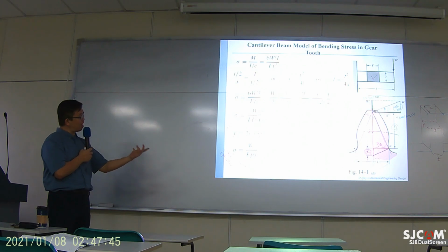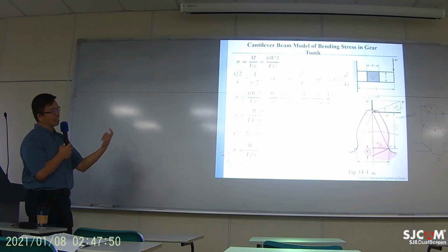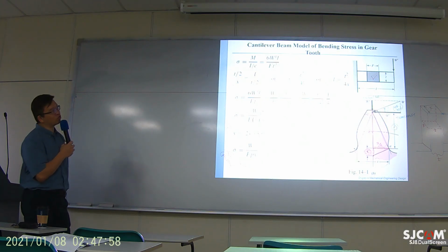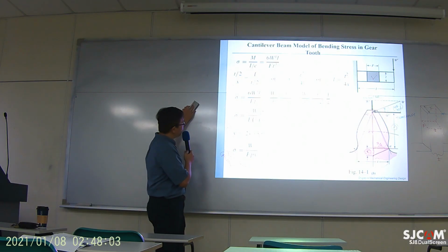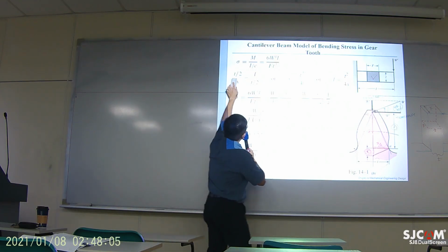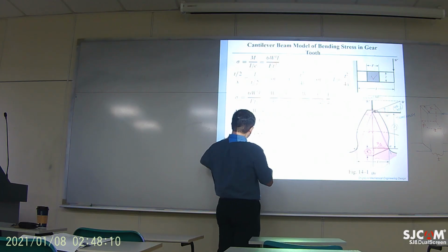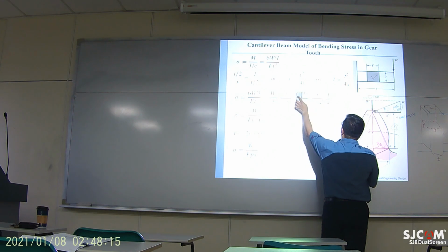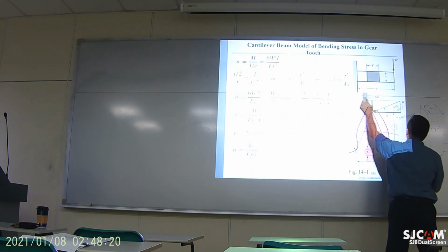You need to know the length, and you need to know T. L and T really depend on the profile of the tooth. So that's the equation of the Lewis factor, and that's due to bending, due to the transverse load, transverse force.